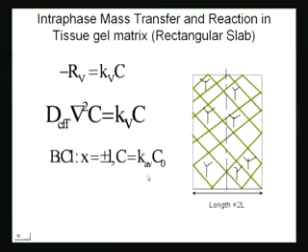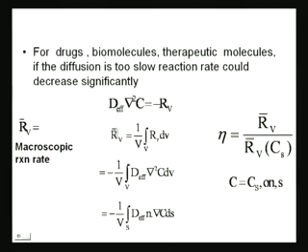So once we are able to do that, then we can substitute. What we do is average out this thing. So here we have the reaction. Let's go back to the reaction. This is the RR that you see over here, the reaction at the small scale, the scale of the pore. If there is more or less uniformity in the concentration, and the pore scale size over the macro scale size of the core is much smaller than 1, then we can do an averaging, which means that we take the reaction rate and integrate it over the volume and divide it by the total volume.